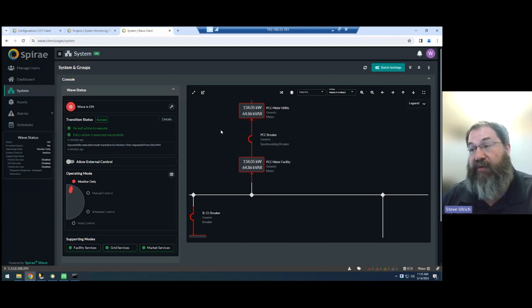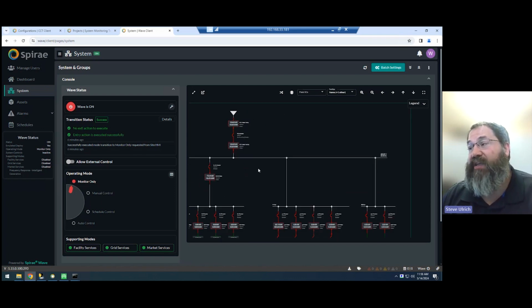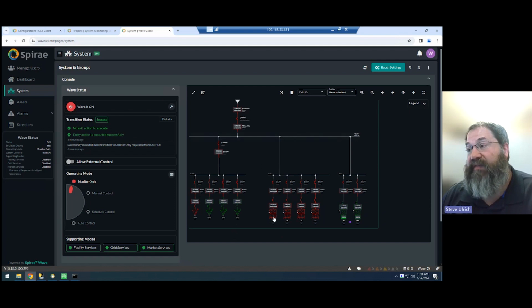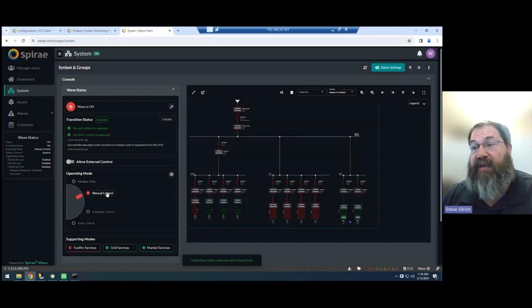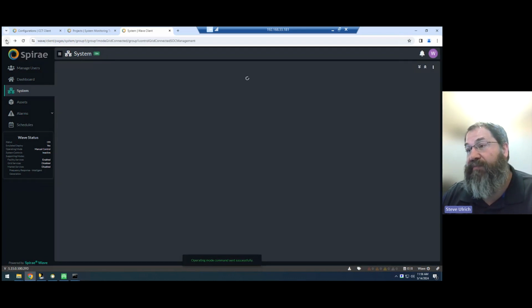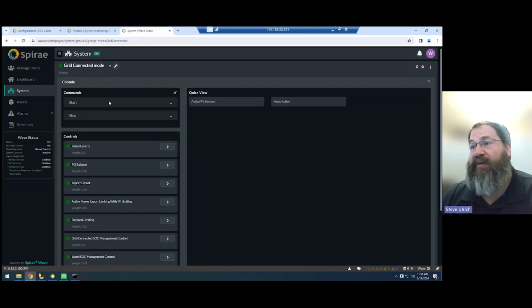and based off of all the rules for your facility, that may not be the decision that you want to do, and you want to actually do something about taking this PV and storing this into your batteries in preparation for when nighttime comes. Then you can actually use that PV production, shift it over to now being inside of your batteries. So if I change my mode here from just monitoring to now actually in a control mode, and then if I go to, we've got a control, let me go back over here to this view.